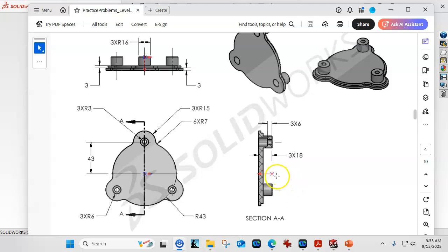So if we draw all of this sketch here and bring the boss this way, or the three bosses, up from the front plane, then build this geometry on top of it, then we could cut back through. Now, there comes a point with the contours and regions where we're going to make this too complicated.